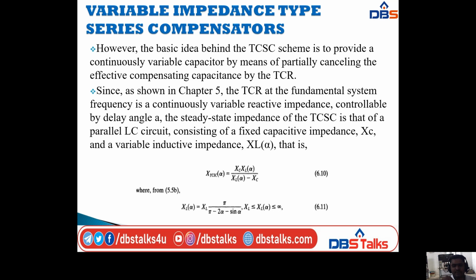From equation 5.5, I am taking XL of alpha is equal to XL into pi divided by pi minus 2 alpha minus sin 2 alpha, where XL is the base value. In this case, XL of alpha is in between XL and infinity. These two equations are treated as 6.10 and 6.11.